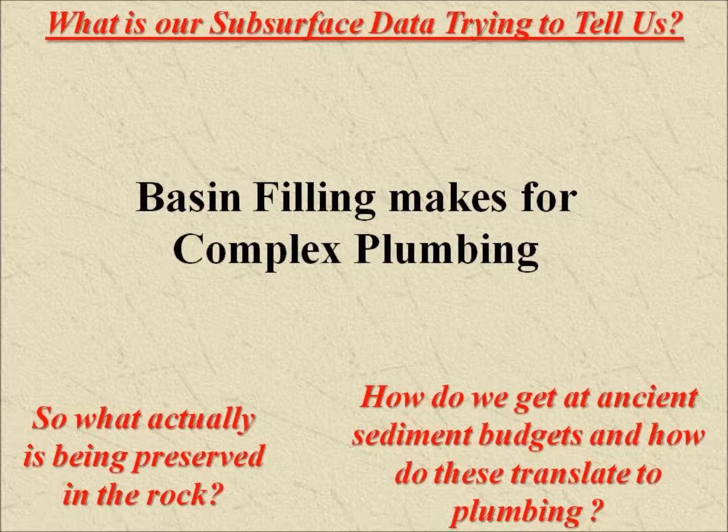And, again, you still end up with breakthrough problems. Yeah, well, I think that's an interesting question, because then the question becomes whether you're worse off having baffles that slow down your overall flow rate, which is bad, or having short-circuiting conduits that speed up your rate, that might give you short-circuit. And I think that's a very valid point, and one that definitely was worth some thought.